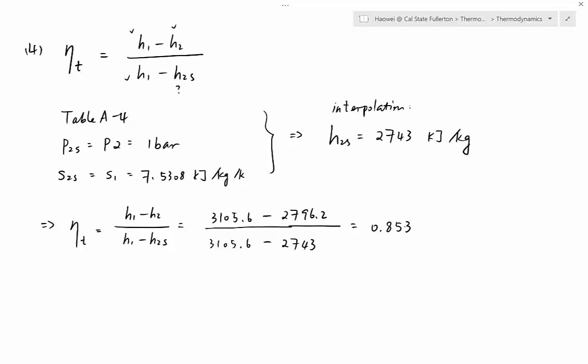Because what does the condenser do? The condenser does nothing but to lose energy, to lose heat. So that's why when it comes to the whole setup, the whole system, the efficiency is low, all because of the condenser. And the second law tells you you have to lose heat. Condenser has to be there. You can do nothing to change that.